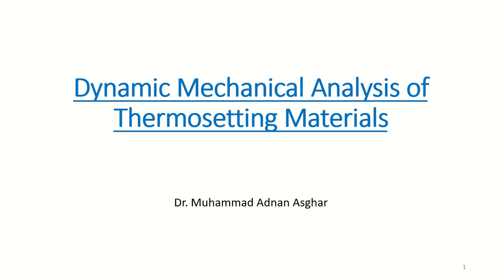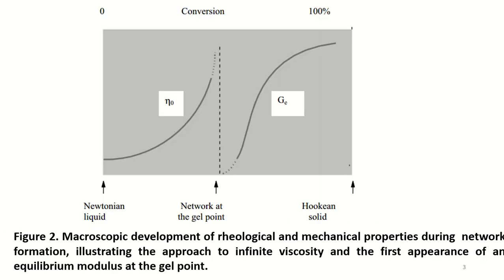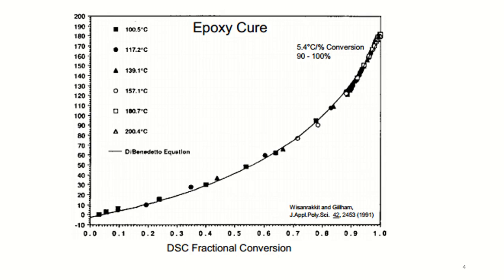We were discussing the dynamic mechanical analysis of thermosetting materials in thermal analysis. So far, we have discussed some of the important aspects of the said topic, which include the two-dimensional representation of thermoset cure and the macroscopic development of rheological and mechanical properties during network formation.